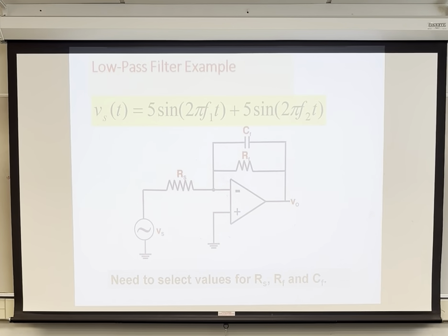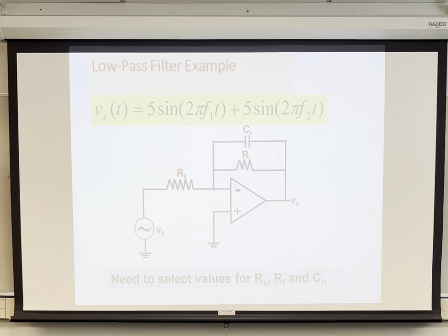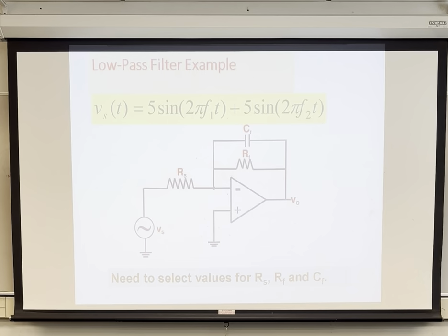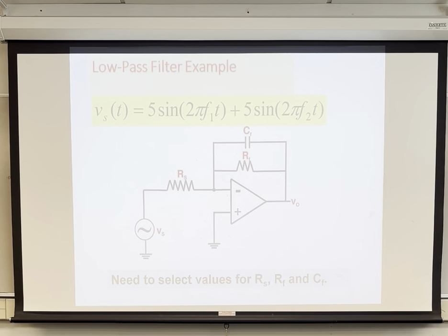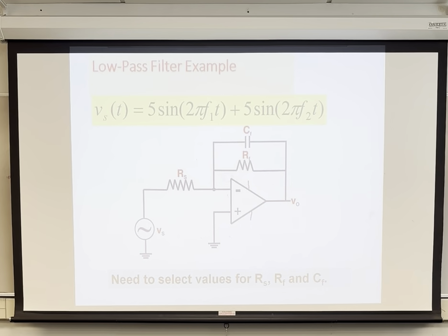So pretty much this is the schematic that you'll be using, with the capacitor and the resistor in parallel, the negative feedback to the inverting input, and of course you'll add your power supplies. When we put this icon on the schematic page, we may have to flip it to make sure we're using the inverting terminal as the input to the circuit.